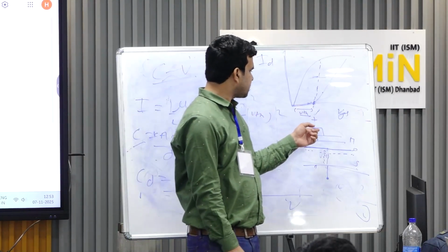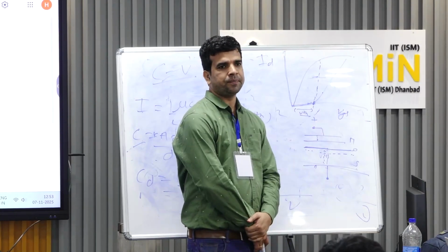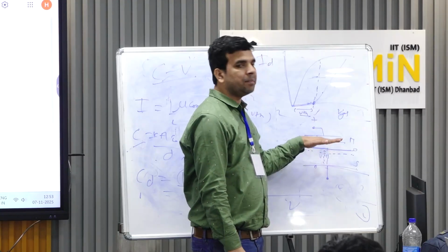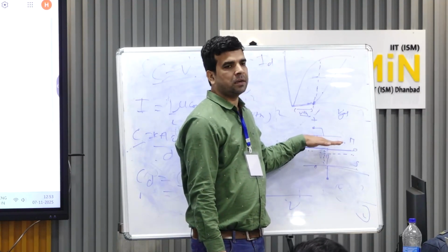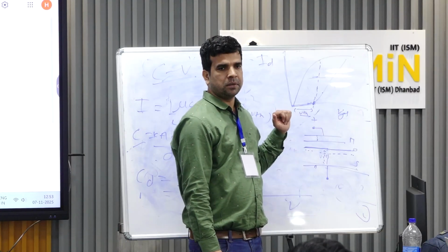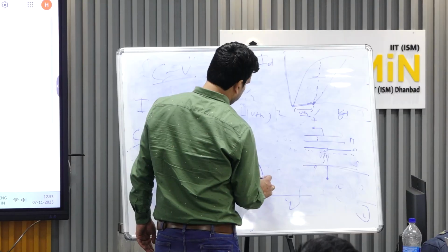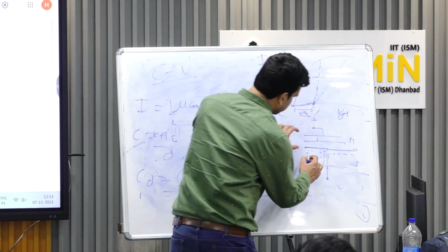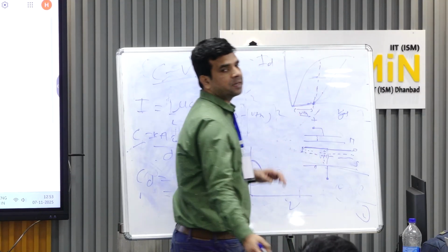But in parallel, what will happen? This positive voltage will start pulling electrons also towards the plate, right? After complete depletion, there will be a point where complete depletion happens, and then electrons start coming towards the plate. At the time of complete depletion, your capacitance will have its minimum value, because at that time you have complete depletion. Let's say this one will come to this point.